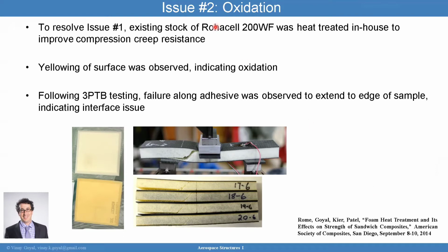What you see a lot of times is, if you don't design your test properly, your loads are going to be too high for a machine. We've seen that before. We've had cameras go out. I mean, stuff happens. When they take that high speed data after the test, I'm nervous until they write it to the file, and have it complete and saved and all that.